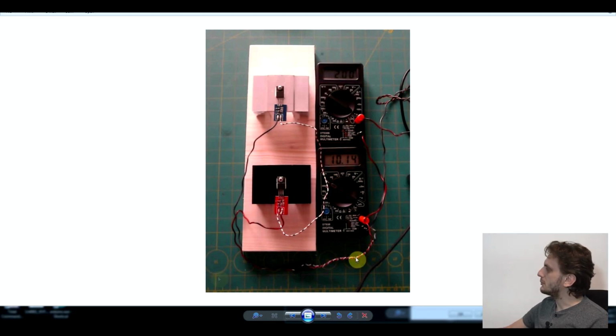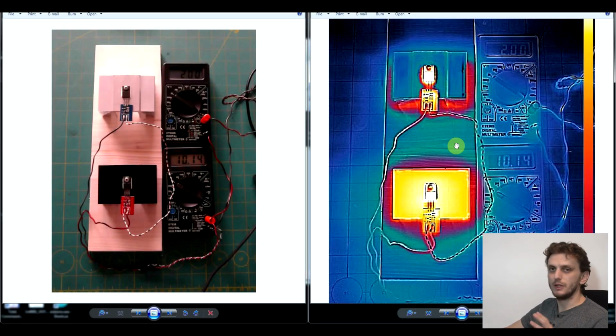Now if we look at this setup in infrared, even without looking at the exact temperatures, we will notice a few things. So we can see that both our transistors are white hot, so roughly the same temperature, but we can also see that the painted radiator seems much hotter than the non-painted radiator. I mean, this is just as blue as the environment, so strictly based on the measurement, it seems that it would be at 20 something degrees, which of course it isn't.